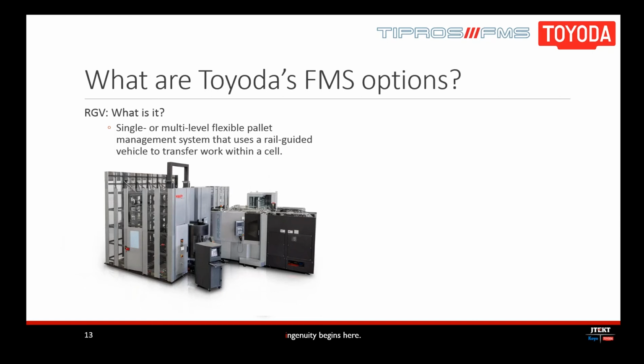RGV is a 1, 2, or 3-level pallet management system that uses a rail-guided vehicle to transfer work about the cell. The cell is multi-generational, meaning that machines that have the same pallet size but different production unit can be integrated into a system. This system is capable of increasing spindle utilization to 95%, which gives shops the ability to run lights out production, which is a huge advantage.